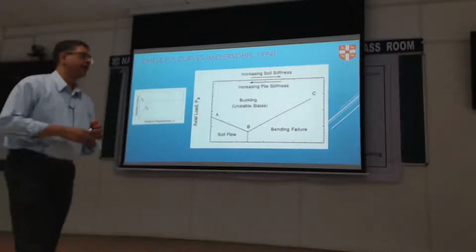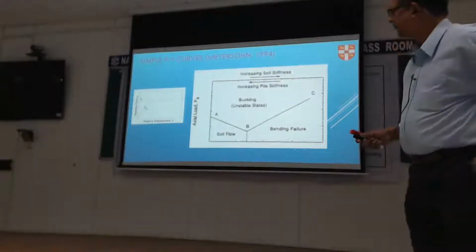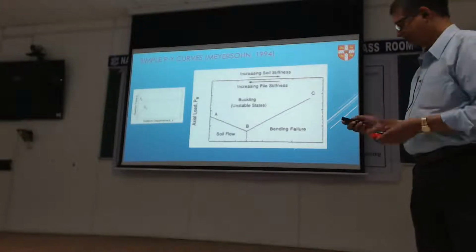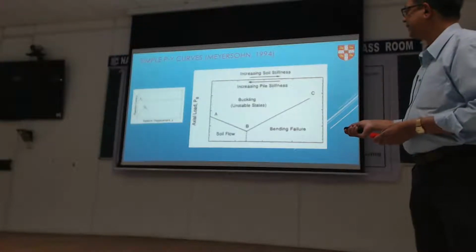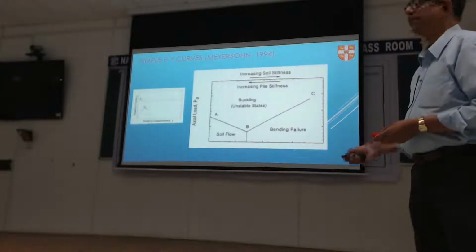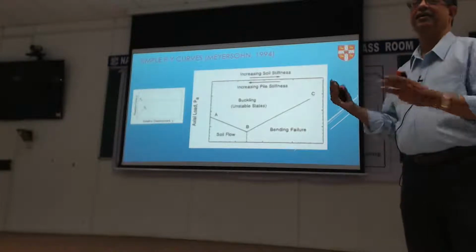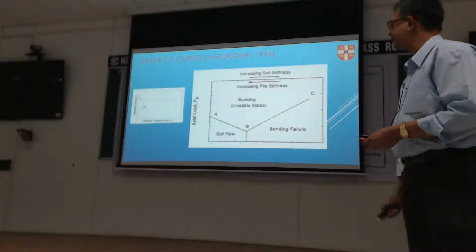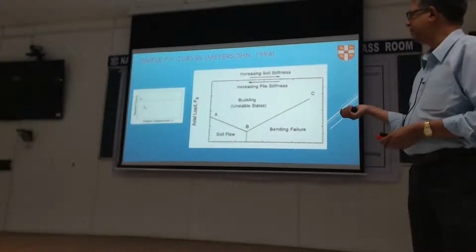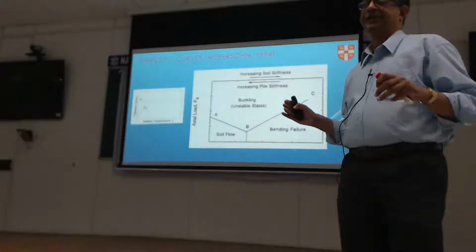He basically said we'll take this reaction force acting on the pile to be linear up to a point, and then stays constant beyond that. So it's like a bilinear fit. And so you've got the reaction force P, relative displacement Y, and a limiting pressure.